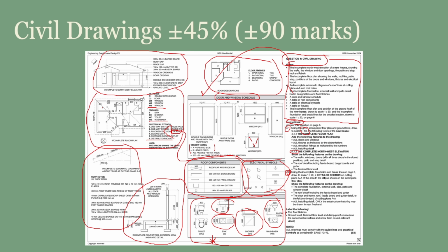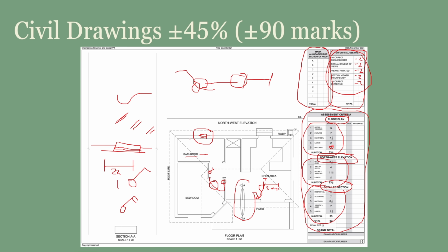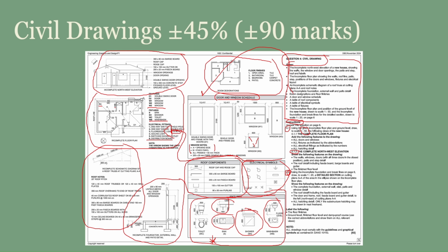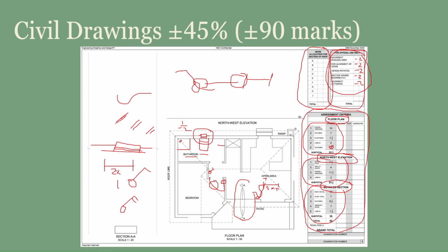If you look in the bathroom, you see that there's an SH, which is a shower. And to draw a shower, it's going to be there in the corner. And you only put in the drain hole. No additional information. Any additional information will lead to a penalty. If you put anything extra in, it's going to be -1/2 for every extra line that you put in. If you look there, there's a water closet. It's a toilet, so it's going to look something like this. And then we have a wash basin, which sits on this wall here. And it's going to look like that.